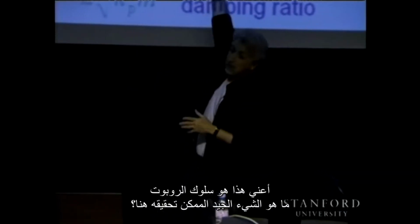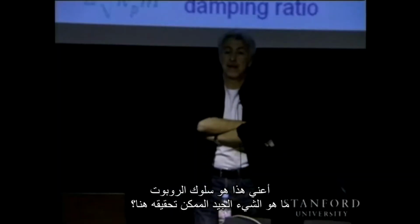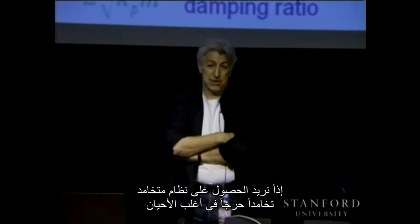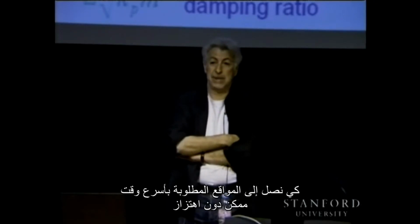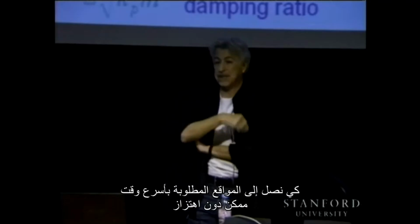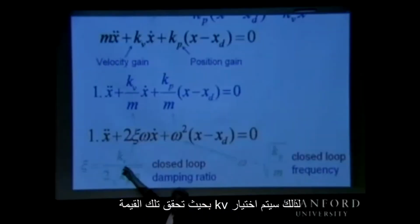Here is your behavior. What would be good to achieve here? Yes? High frequency and critical damping. So we want to have a critically damped system most of the time, so we will reach those goal positions as quickly as possible without oscillation. So kv would be selected to achieve that value.